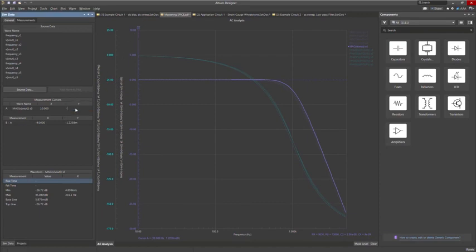And if we want to add a cursor again, let's go to my 3 dB point, or my negative 3 dB point. We can see that I'm actually past this 1000 hertz. I'm at 1.1. So it seems that these capacitors are affecting, they're pushing the cutoff frequency later. And actually down here, we'll notice that the resistors have the opposite effect. They're pushing it earlier.